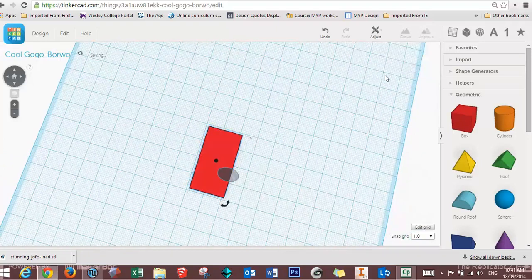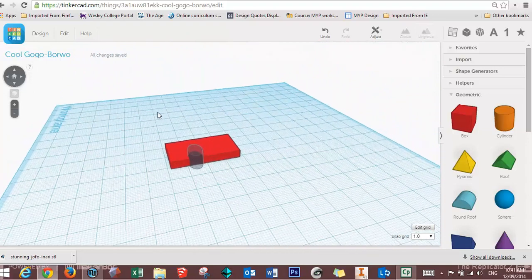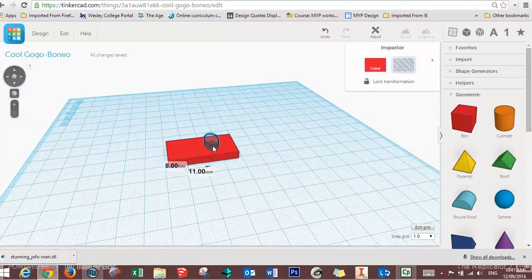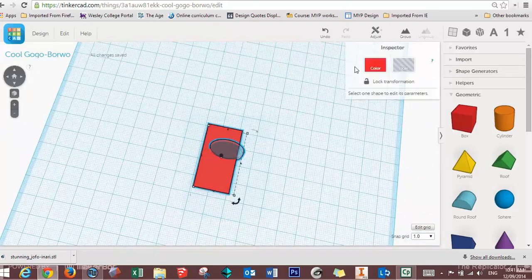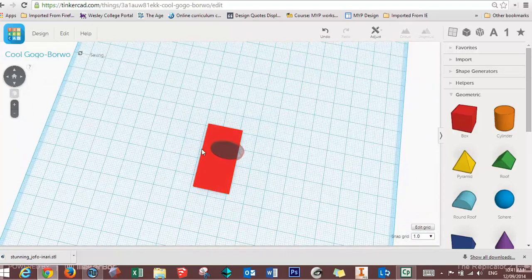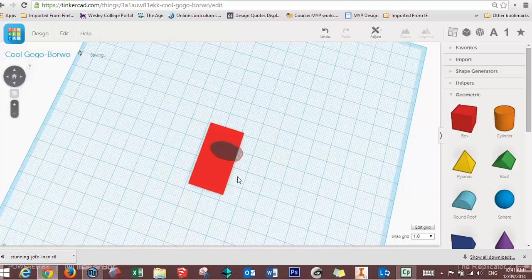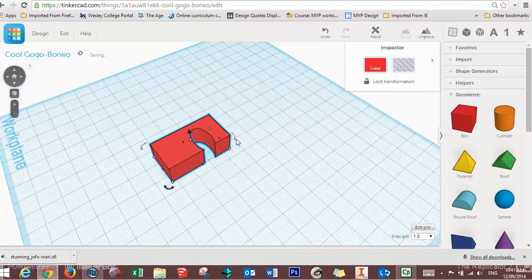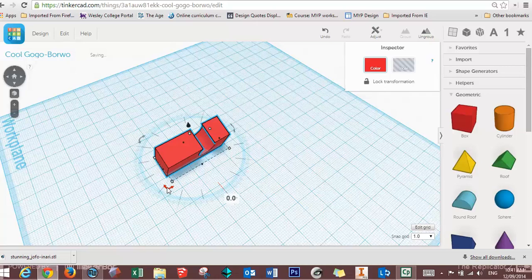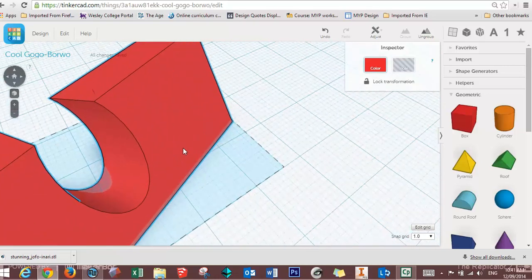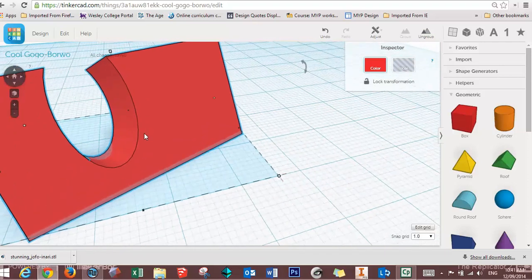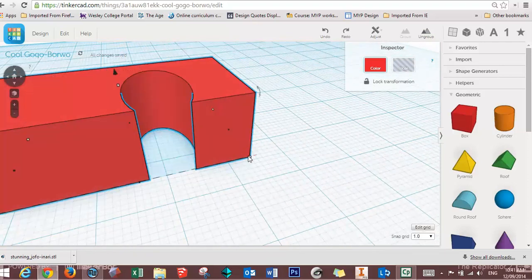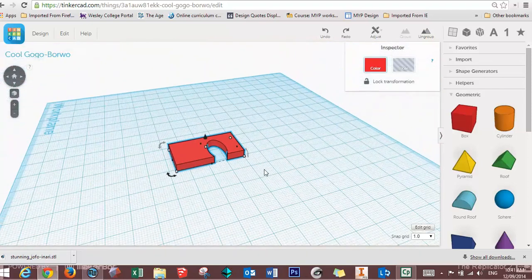So when I ungroup, the original cone shape, or little shape, is still there, and I can move it around and resize it. But when I 3D print, it doesn't print and just comes in as a whole. Select them both and regroup, and it'll take that bite, if you like, out of the geometric shape. There it goes. That can now be resized, moved around, spun, and had anything done to it that you would like in readiness for 3D printing, and that will 3D print quite nicely. Control Z to undo. There is an undo button at the top as well.